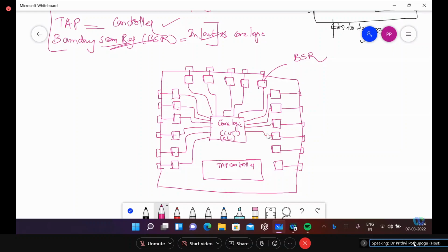Normally the wires won't be running in parallel if you see that in practice. Why? Because to avoid the induced EMF, the wires won't be run in parallel in practice. You can see this in the wiring.